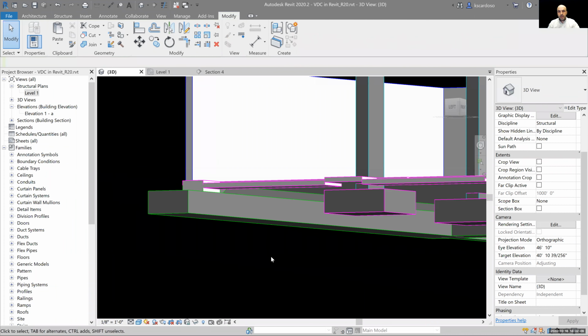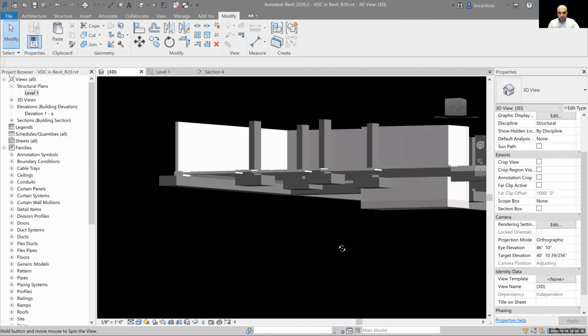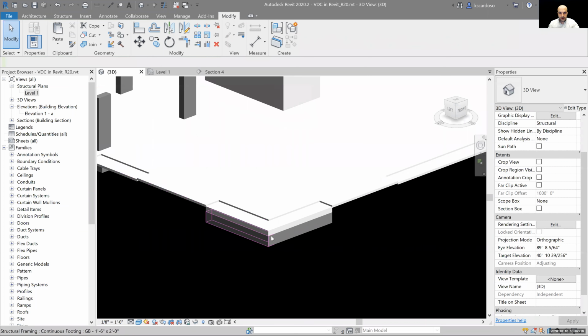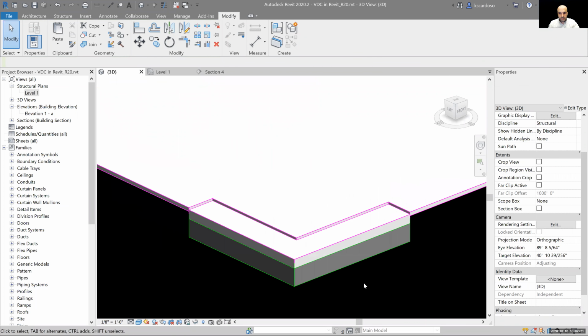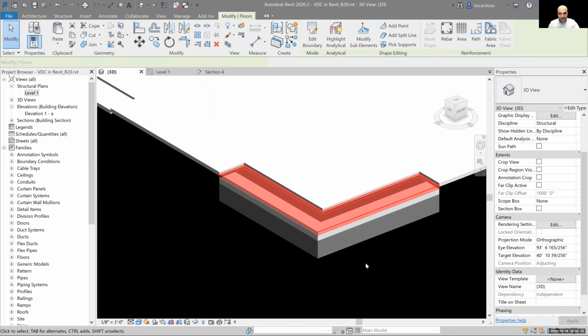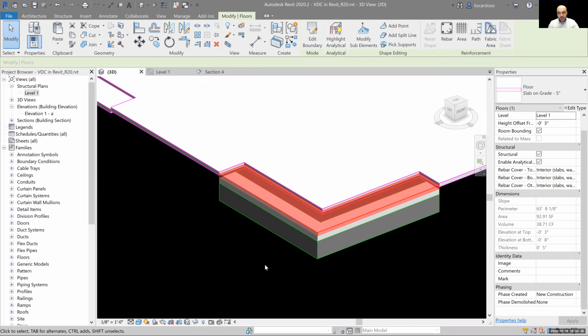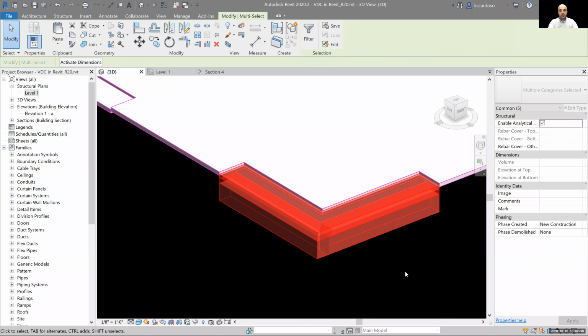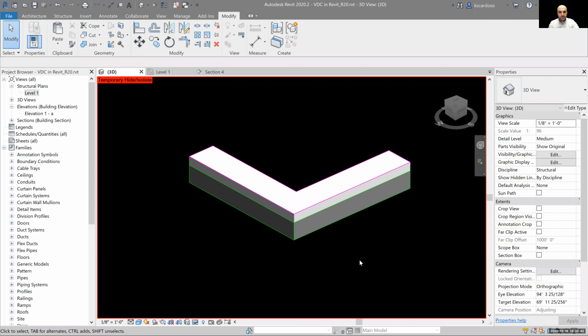So a note about beams in Revit, because that's what we're using, right? Let's go to this corner here. And I'm going to just isolate this corner patio with the 1, 2, 3, 4 beams there, 2 thickenings and 2 grade beams, right? So I'm just going to select this little corner condition and I'll hit isolate element, IE. This is all I'm looking at.